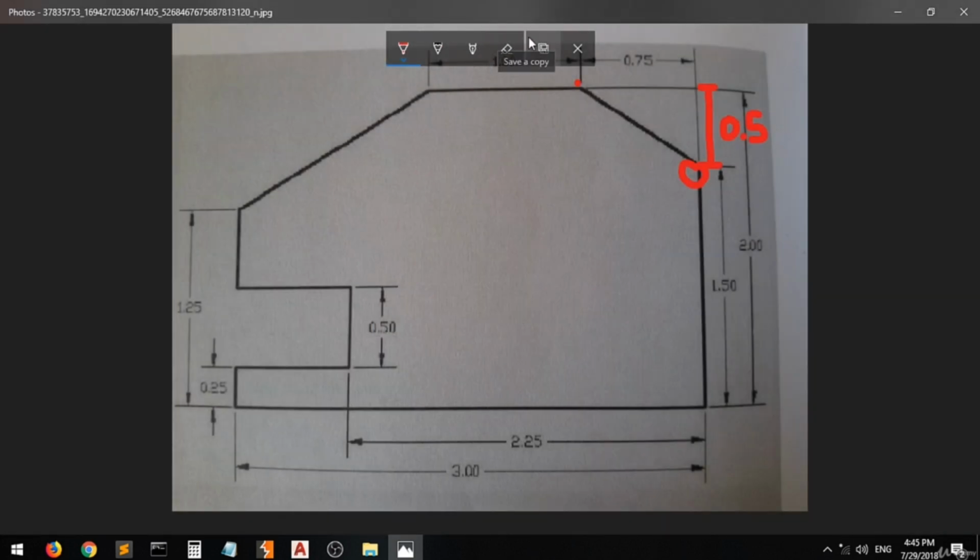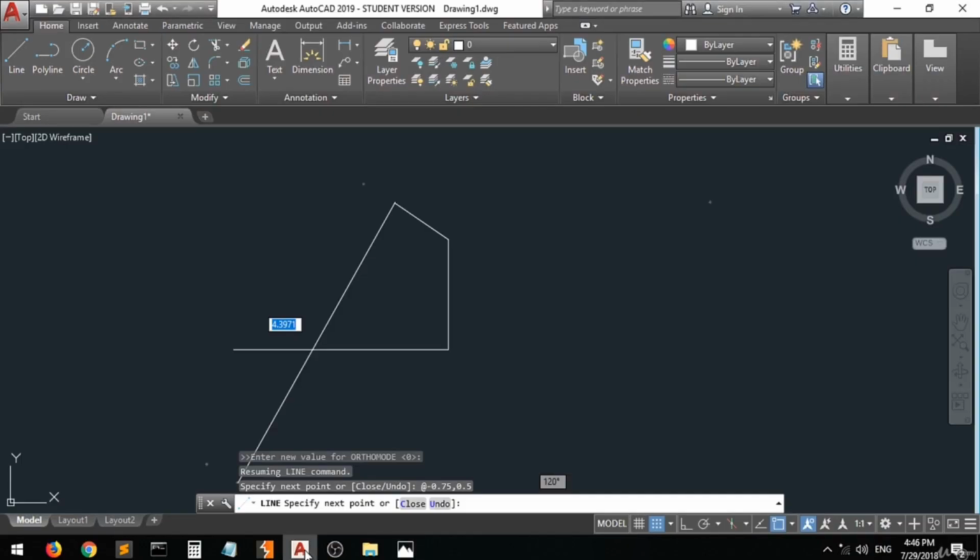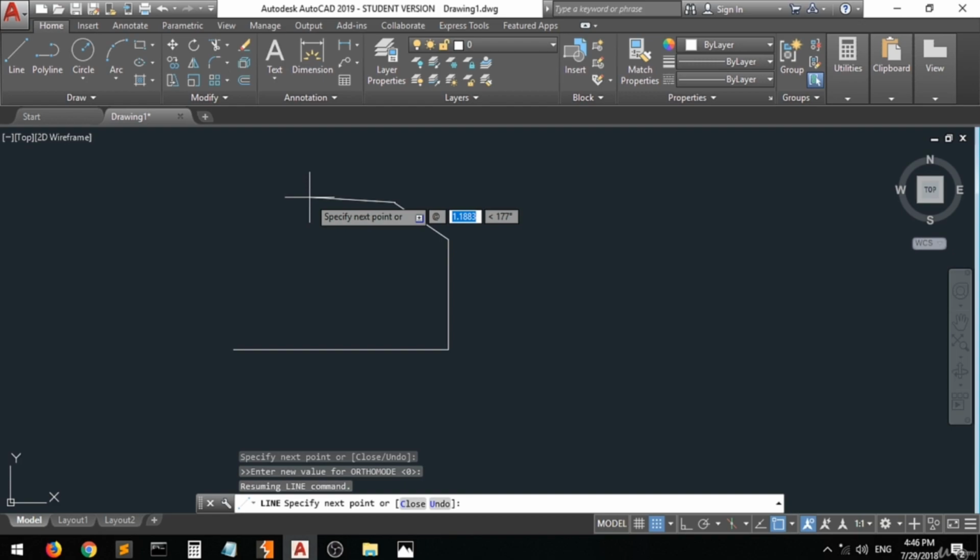How are we going to move from here? As you can see, the length of this one is 1. So let's create a horizontal line with a length of 1. You can enter it with either the coordinate entry or the polar entry. Let's do it in both. I will start with the polar entry. We do @ and the length of the line, which is 1, then a smaller than sign. Then the angle of this line will be what?